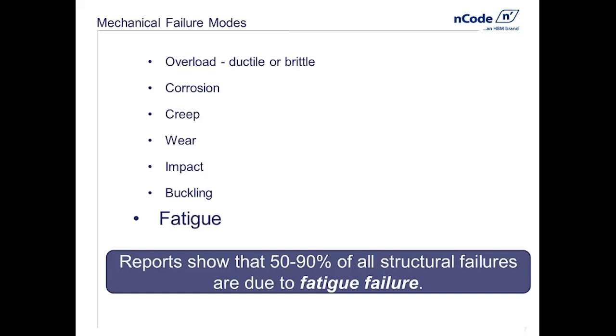that happened beforehand. So fatigue is a cumulative failure mechanism, and because of that, it's much more difficult for us to design against deterministically, or to look at a loading scenario and understand, will that cause a failure or not? It's all the accumulated fatigue cycles over time that are going to cause a problem for us. So we need to address this.